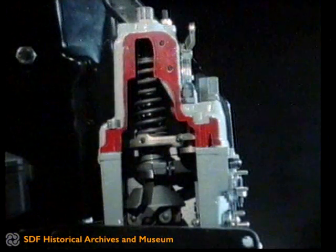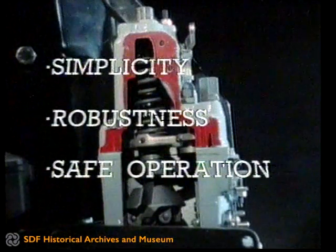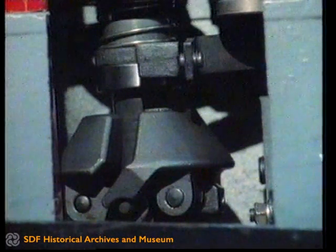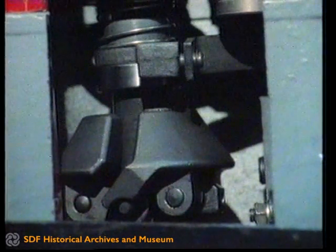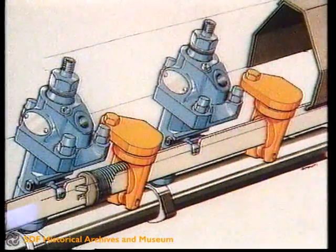Regulator. The regulator is mechanical with counterweights. Simplicity, robustness, safe operation. It is formed from a module independent of the engine in a well-protected but easily accessible position, and can be fitted and dismantled easily and quickly. Easy servicing and calibration. It is operated from the camshaft and rotates at high speed, the same as the engine, thus allowing the use of more compact counterweights, giving a more prompt response. It incorporates the automatic supplementary fuel feed device for starting the engine.